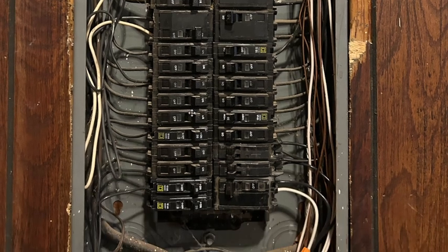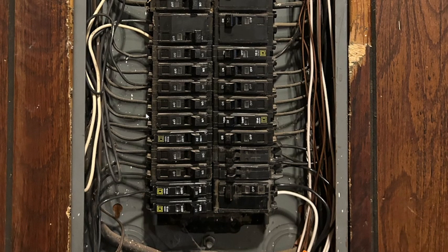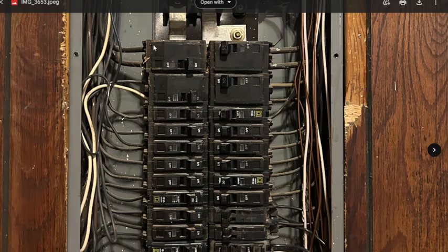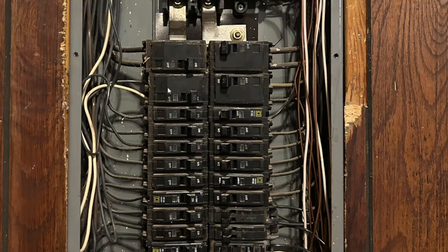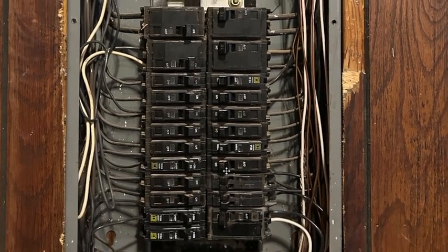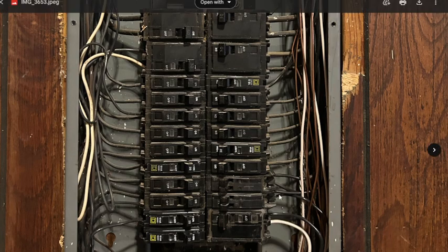So they are full. In fact, not only are they full, on some spots, like counting on the left-hand side of this, starting with the first double breaker, second double breaker. After that, if you count 1, 2, 3, that breaker has 2 wires on it. And if you look at the bottom right of this panel, you have the same thing going on. So just to point out, not only was this full, they already were doubling up.